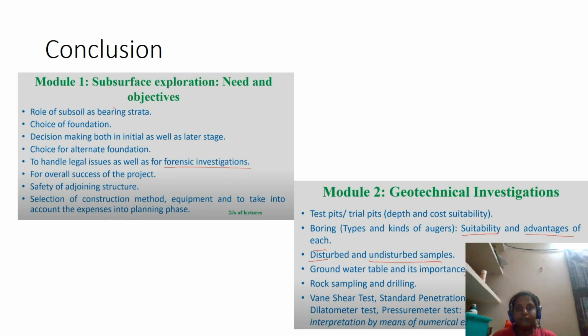Only if we do soil testing will we know what choice of foundation we could make. Soil is a natural material and it could have a lot of surprises when we start construction. So it is very important to know what lies below the ground, where we are not visually able to see, whether it's a rocky stratum or a soil stratum, a weathered rock, or whether any pipelines, utility lines, or an abandoned well could be lying below.